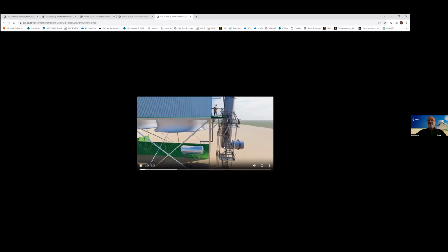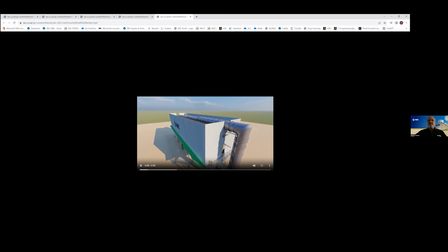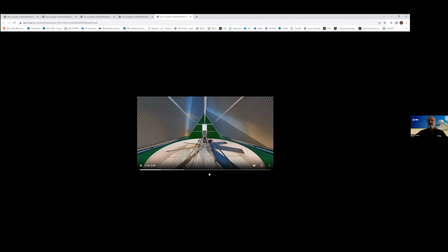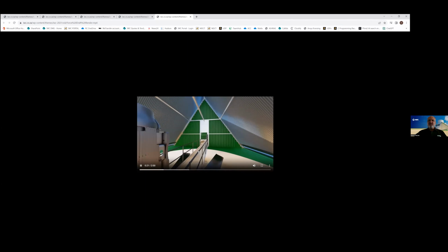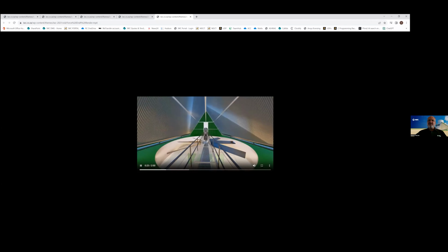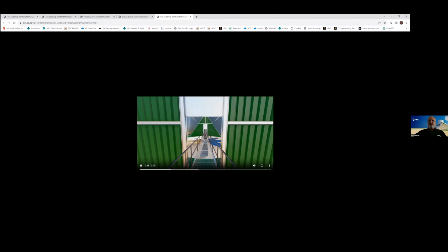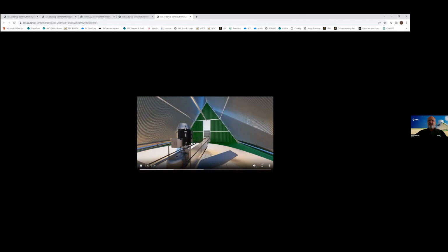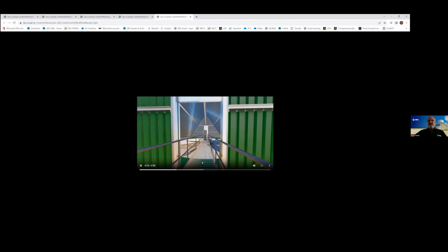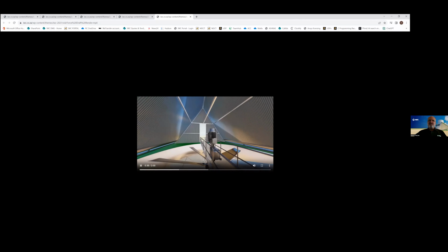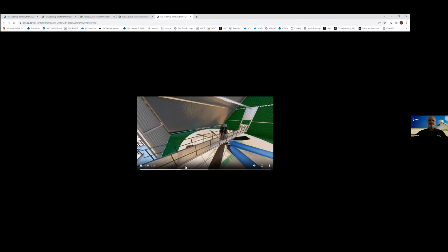The steam duct takes the steam from a steam turbine all the way to the fin tube bundles. And these bundles are housed here. These are the bundles I showed you earlier. Then one has a wind wall around to shield the bundles from the wind. Here we're inside, you see the fan bridge, which has the fan assembly. There's a motor, a gearbox, and a fan. The fan runs inside a fan ring or a fan casing. And in between each unit, you have these plenum partition walls.